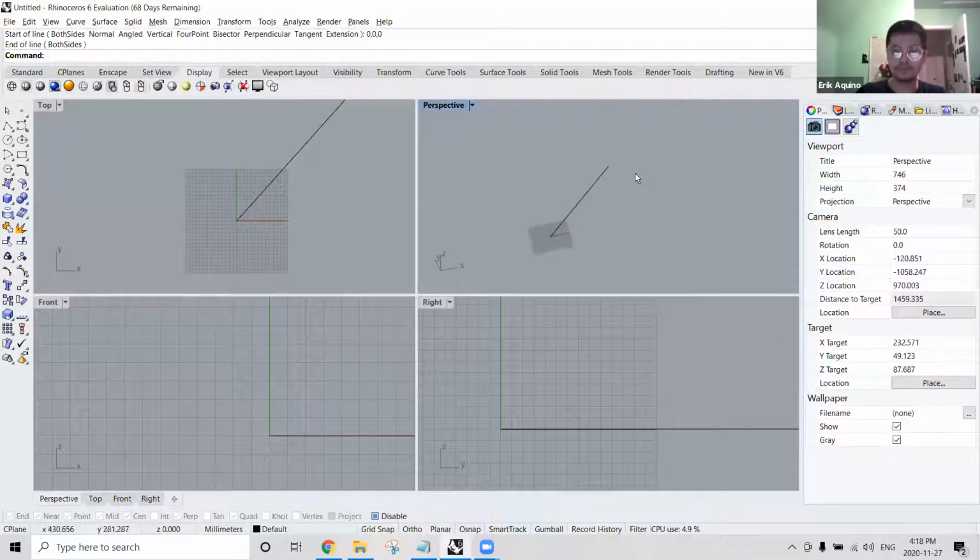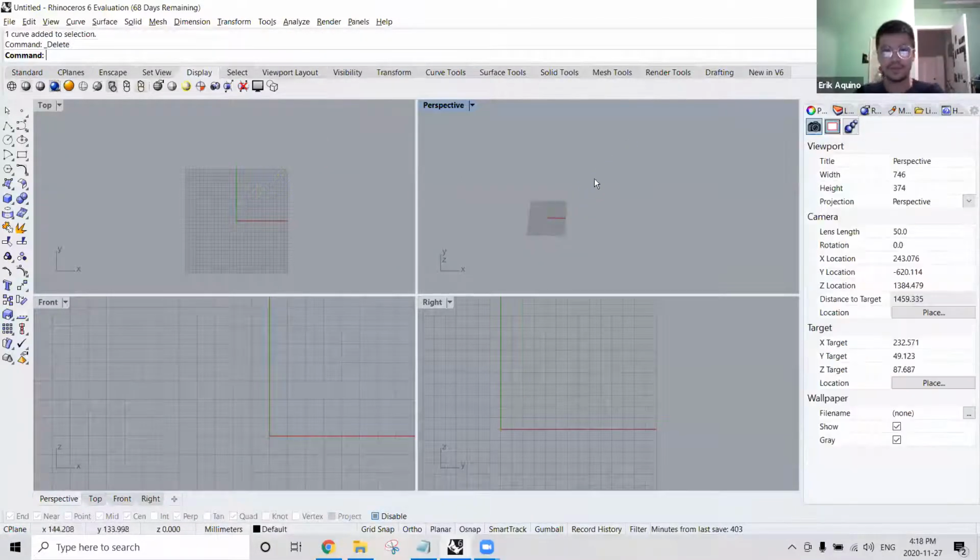So there essentially are 3 ways to create your objects through a command. We can manually click within the 3D space, and that's not that accurate, but we could gauge the angles and all that. We could use our coordinate system, which is very precise, by choosing specific points in our 3D space using the X, Y, Z coordinates. And in some commands we can define the value of a length. So, yeah.